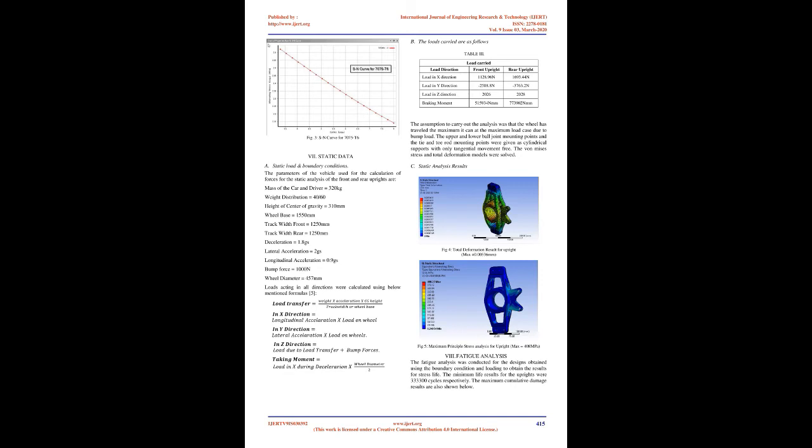In real case scenarios, the mechanical components of race cars are subjected to variable amplitude loading, and the loading pattern cannot be predicted with a characteristic equation. Thus, several methods have been developed over the years to take into account the variable amplitudes, using the data generated by physical tests of constant amplitude to predict the life and damage.